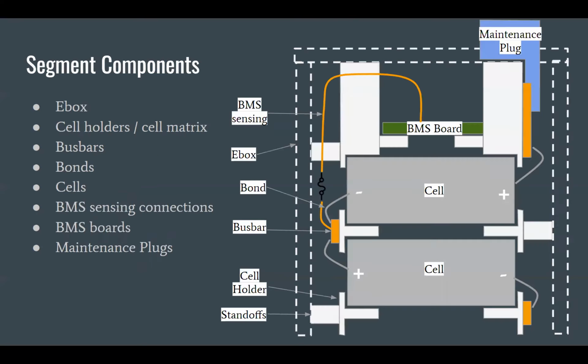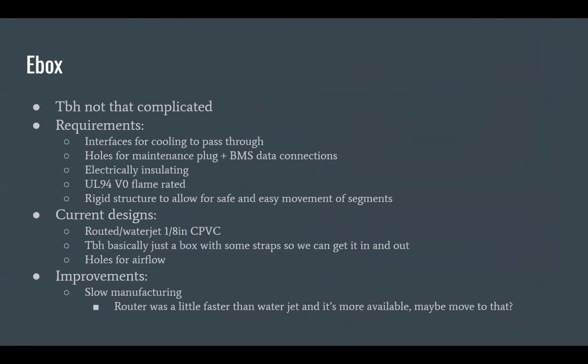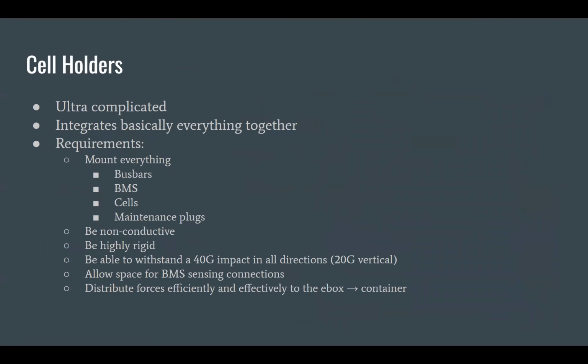Especially if you're looking at that visualization, you see that even though the cell holders look like there's a lot, in reality there isn't really much material in here as a honeycomb structure. It's actually pretty thin. And so even though we're dealing with one of nature's strongest structures fundamentally, getting the actual forces in FEA to all line up so that it can handle the 40G loads in all directions is quite a bit of work, quite a bit of effort.